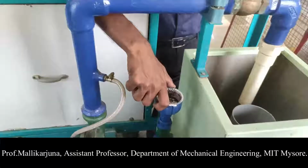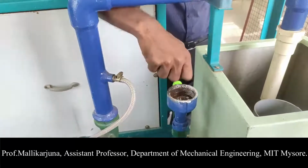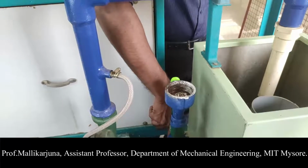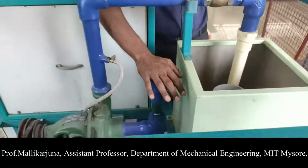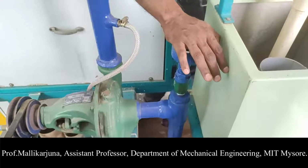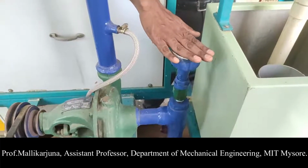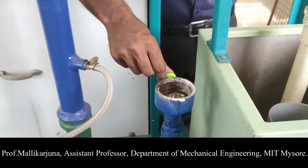That is, if I have to start the device now, then I need to make sure that throughout this suction pipeline the water is filled, or else if I start without filling the water, the air may rush into the pipeline. That may cause the priming problems. So because of that, initially we need to make sure this pipeline is filled with water, and this valve needs to be closed before conducting the experiment.